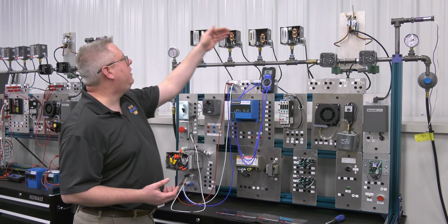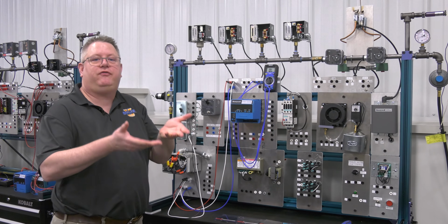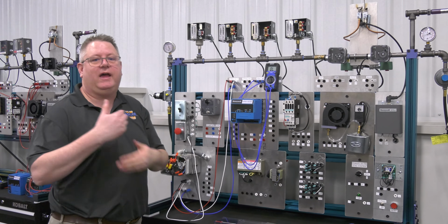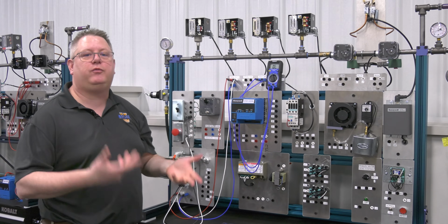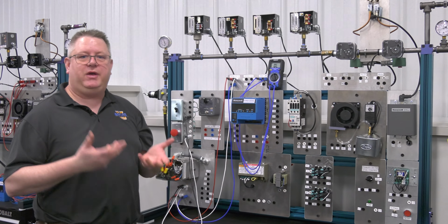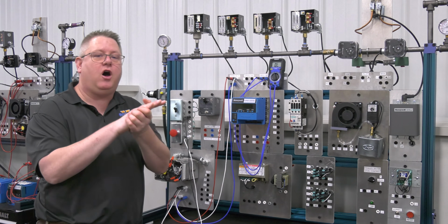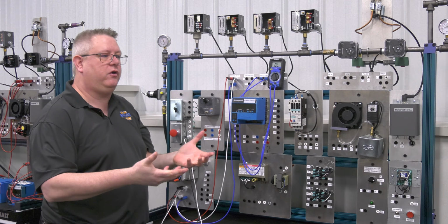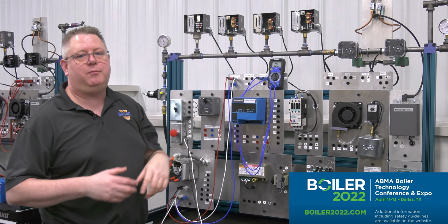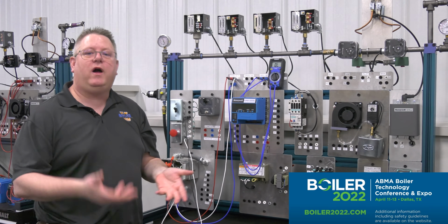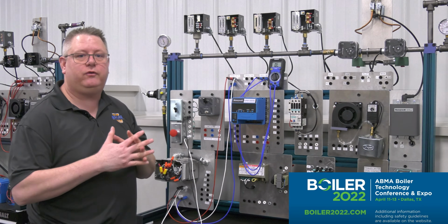So how much above the operating pressure control? We certainly want it set enough that in normal routine cycling of the boiler, we're not having to come out and reset the overpressure switch. If we've got big load swings and we have loads that suddenly shut off and that swings the pressure on the boiler, we may want to give it a little more margin. The idea is basically we want it to be something that brings our attention to an issue, not a routine thing.